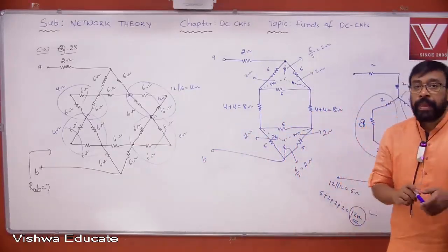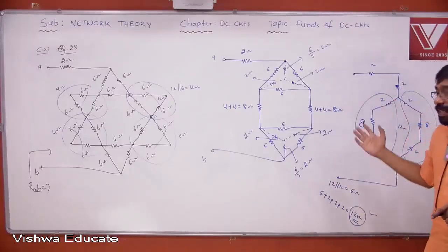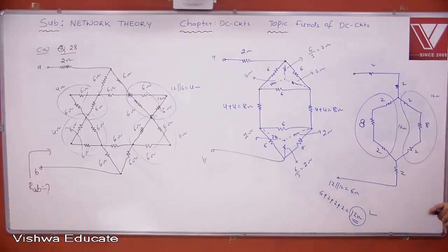Yes, I think all of you are clear, so please note down quickly. Whenever you are applying reduction, first you check. The first important step to check is whether we can use a normal series parallel reduction. If it is unavoidable, then we'll go for what? Star delta transformation.